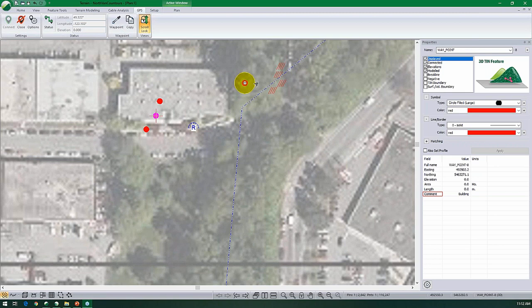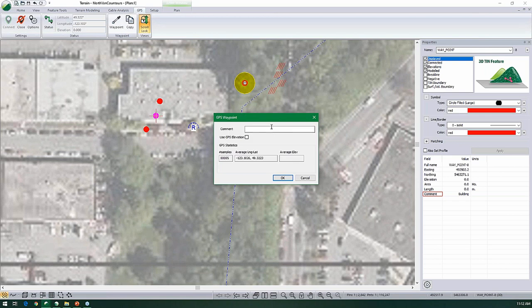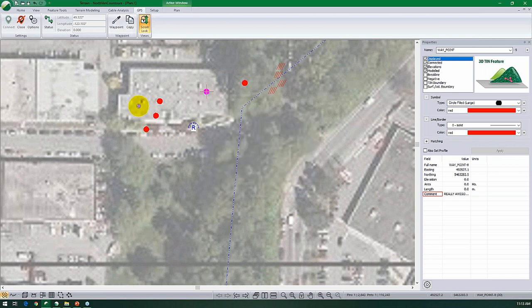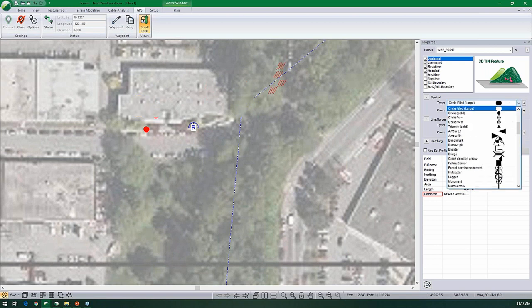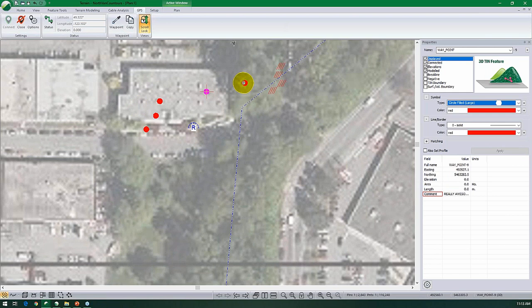And this is a really great way, when you're out in the field with your GPS, to sample a waypoint, to add a comment if this was a really awesome location. But for the purposes of showing a waypoint, we can add that GPS waypoint. It creates a new feature here. It says really awesome location. These ones over here, they've been tagged as swamp, borrow pit location, and you can even go ahead afterwards and change the symbols that you have for the different waypoint locations.